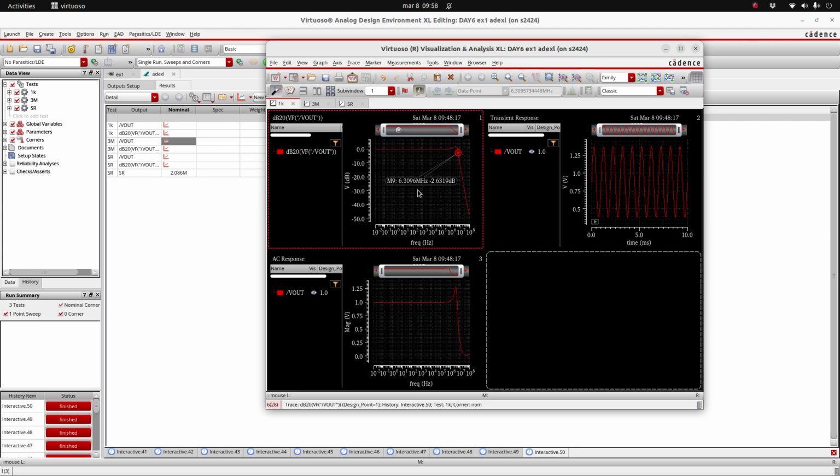But we have to be extremely careful when we see these kind of numbers, because remember that the AC simulation is taken with linearized models, with a linearized circuit, so it doesn't tell us absolutely anything about the linearity of the circuit. So we really have to test if we in fact can put signals at very high frequencies, and if linearity requirements are going to be accomplished.